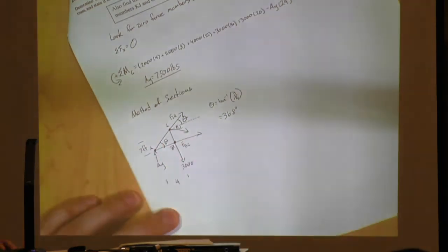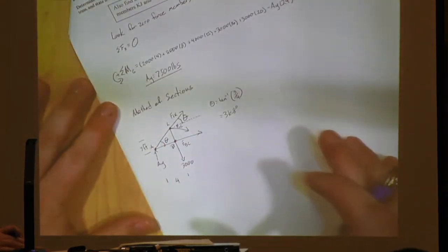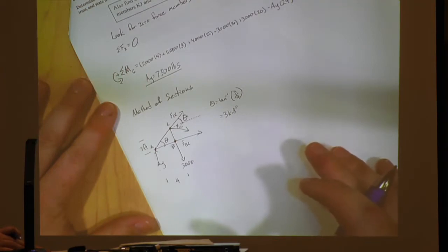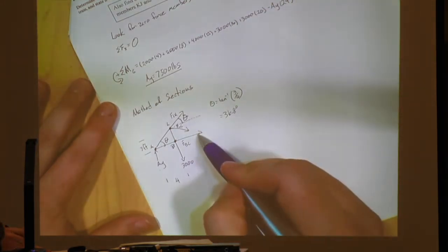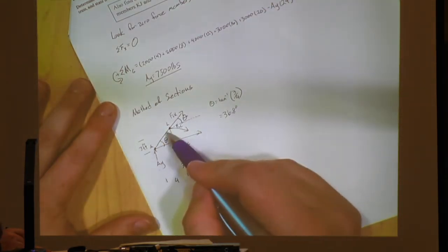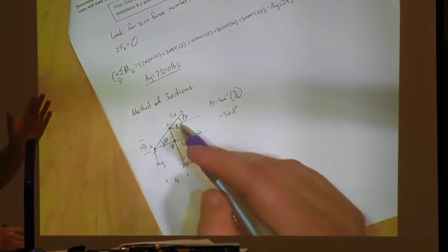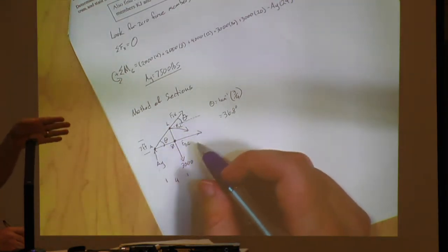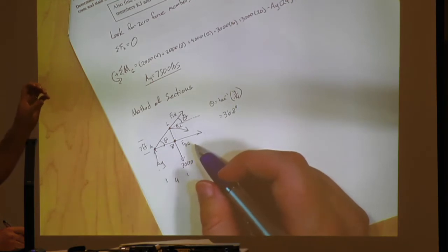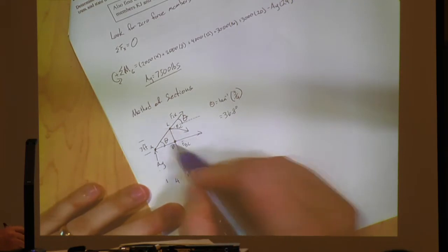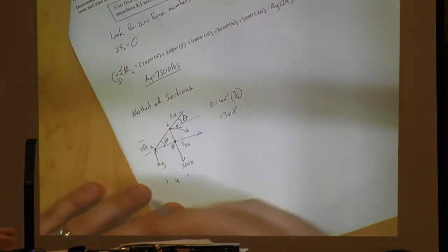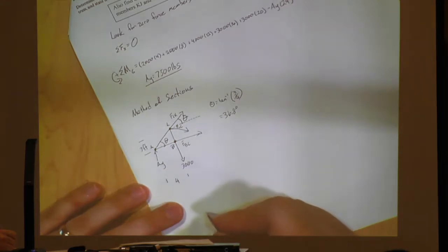All right, so we can solve for one of the members right off the bat. Which member is that? So AL is part of the rigid body, remember? So when we do sections, everything that we don't cut and looking for the internal forces for gets treated as a rigid body. So we actually ignore it. So we're looking for these forces, right? Can we actually solve for a force right off the bat? Yeah, we can solve for BC right off the bat doing what?